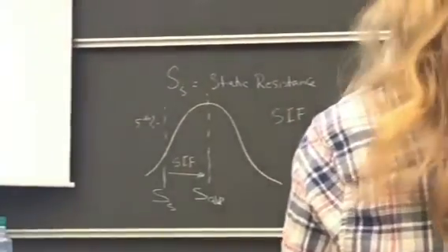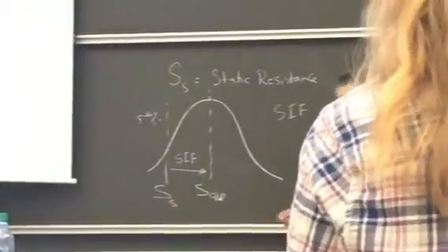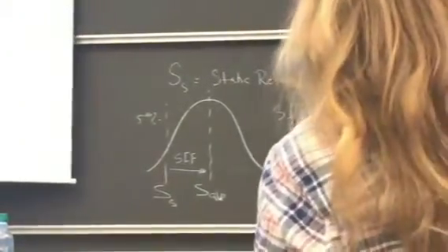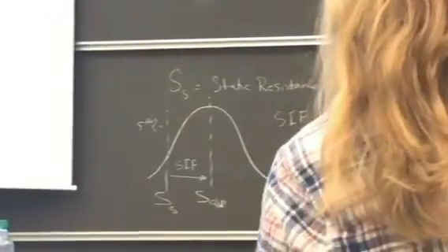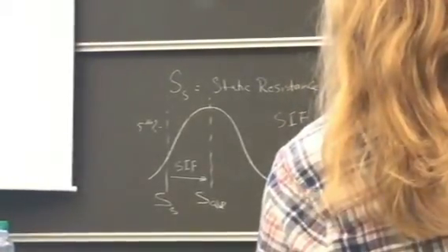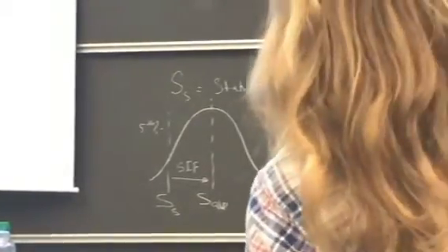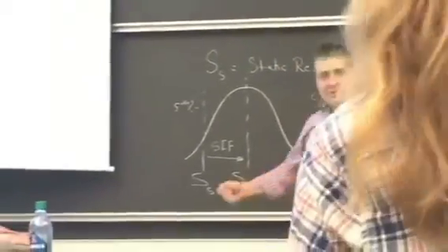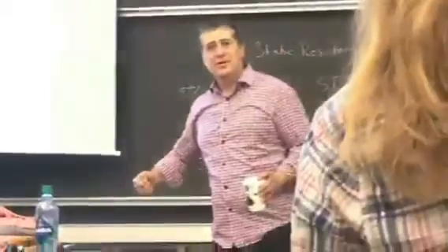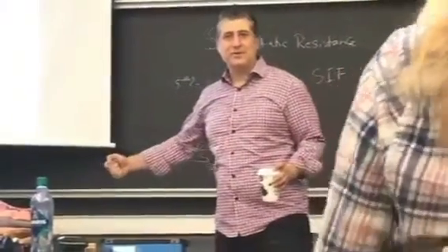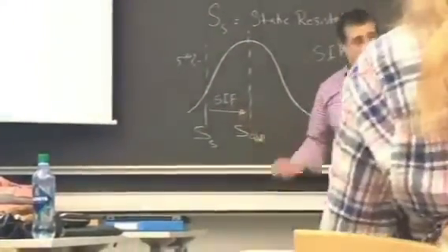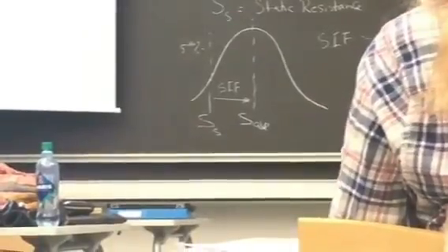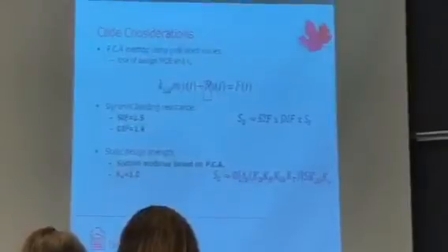And the other one is the dynamic increase factor, which takes into account the, I should have brought you coffee, all of you. So the dynamic increase factor takes into account the strain rate effect. Okay? The fact that the material is not going to behave the same under dynamic condition as it would under static condition. So that's the dynamic increase factor.